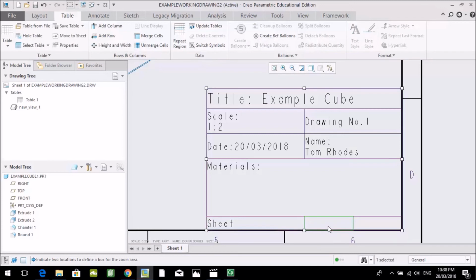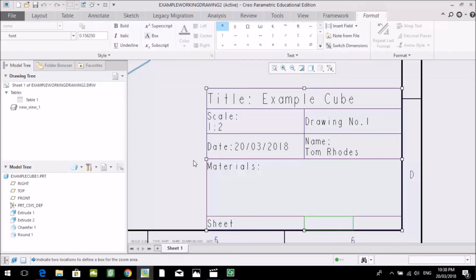Now in our sheet, we're going to go to sheet number 1, and at this stage we only have another sheet, so the sheet 1 of 1. Just be sure, as this was left empty in the format, to change your text height to that specified in AS 1100, so 3.5 millimeters for subtitles. So 1, then we want to change this so it's in